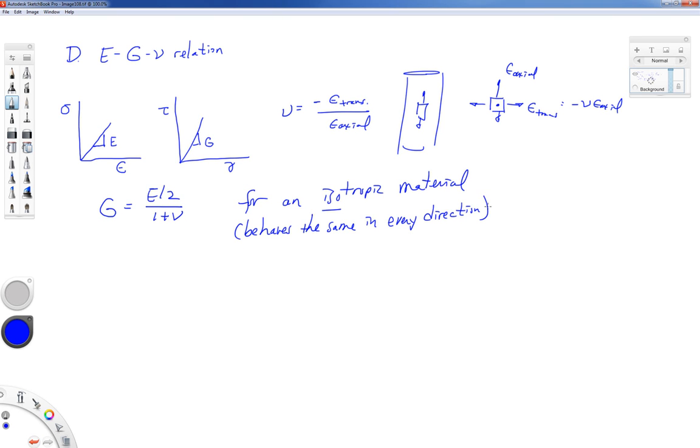Now, a lot of materials behave differently depending on the length scale that you look at them. A lot of polycrystalline metals, if you look at a region of several grains of the metal, steel, aluminum, whatever, can act as an isotropic material. They can behave the same if you pull them up and down or left and right, and so forth.